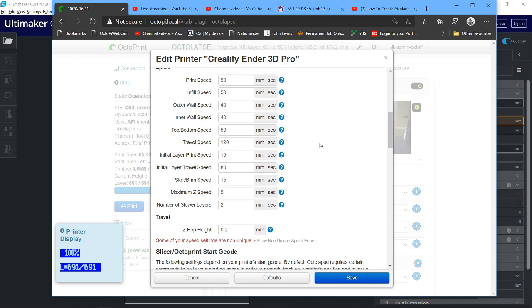So that's why it needs a lot of these settings, so it can simply move it out, park it effectively, take the snapshot and come back. And you only lose about a second. It's about half a second, maybe a little bit more to drive away and half a second or so to drive back. So you do lose a bit of speed because effectively per layer change, it is making a snapshot, and that's about, let's say, a second per snapshot, maybe a little bit more of what you're going to lose.